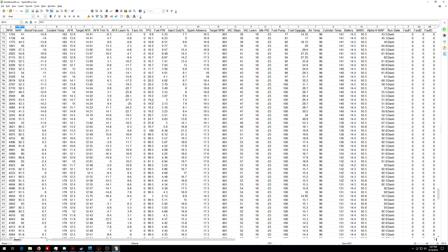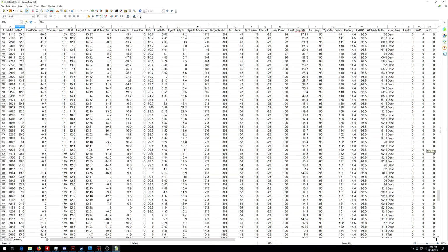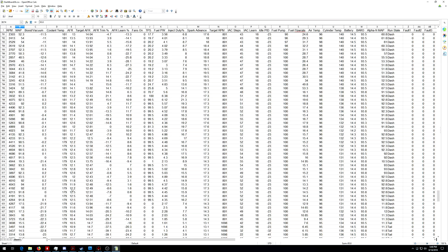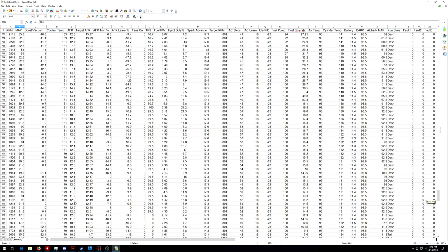So this is the final hit that I did, where I rolled into it from second gear, full throttle. It again went to a very rich condition, and it hesitated a bit, and then I pulled it all the way through third gear, and it started to clean itself up by then. You can see 12.4, 12.5. Fourth gear, it got a little bit rich up on the top at about 4,000 RPM, but for the most part, our AFRs were reasonable. And again, it's important: first gear, second gear, third gear, fourth gear, automatic, pull your run, and see what it's doing so you can make your adjustments.